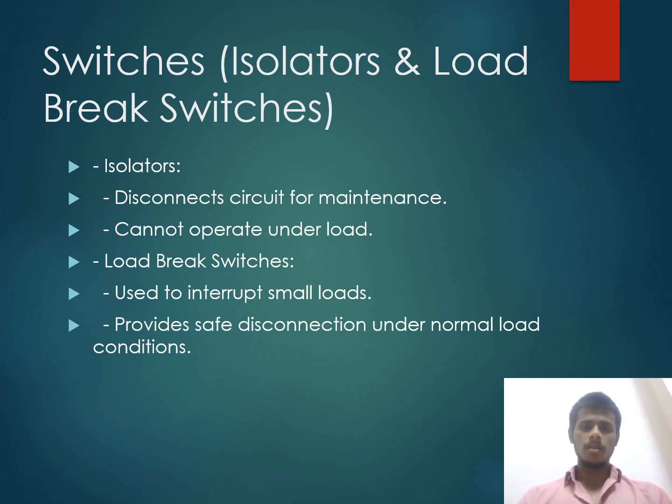Switches. Isolators disconnect the circuit for maintenance and cannot operate under load. Load break switches are used to interrupt small loads and provide safe disconnection under normal load conditions.